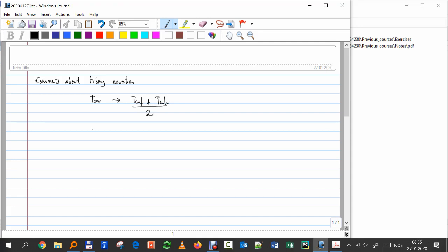And Z average, the same thing. Z average will be the deviation factor at flowing bottom hole plus the deviation factor at the wellhead divided by 2. So that means that I need to have some temperature estimate beforehand. Either I measure or I make an assumption, because I'm not solving in this equation the energy equation. So just be aware here that an estimate of TWH is needed.